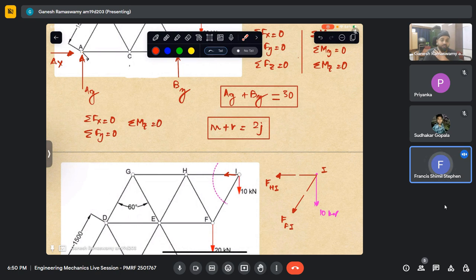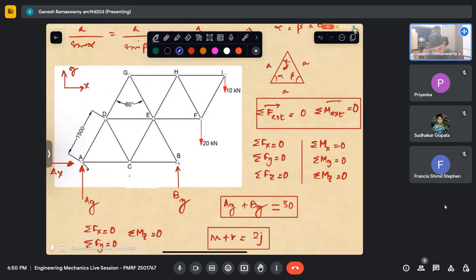Yes. For simple cases, for simple trusses that we are dealing with in this course, if it is following triangles, it will most likely be stable. The thing is, if we go for complex cases where I showed a truss where connections are like these, and then if we go to 3D truss, then it will become more involved. But for the purpose of this, you can consider that if you look at triangles and they are forming neat shapes, then there is no problem.